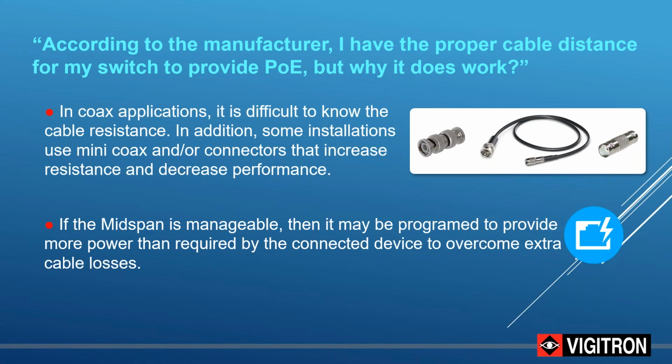However, using our programming within our midspans, we were able to increase the power from 15.4 watts to 30 watts, class 4 IEEE 802.3at, which increased the detection pulse voltage as well as the power. But we were able to put in a headroom signature so that if thermal runaway occurred, if shorts occurred, it would act within the parameters of the IEEE and shut down. So there's another factor where we can overcome installations.